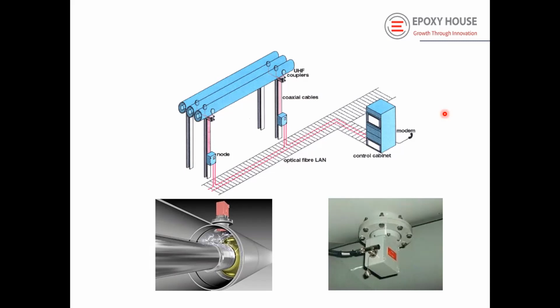They are coming up with fluoro-free gas, because some manufacturers have come up with a fluoro-based gas that has a lesser global warming potential effect, so they wanted to go without fluorine-based gas. They have already done some type tests up to 145 kV, and I'm not sure about 245 kV and above whether it is commercially available. I think from 2012-14 onwards the research is on, and it has not fully replaced SF6 at the 420 kV level or more. There are many gases available.